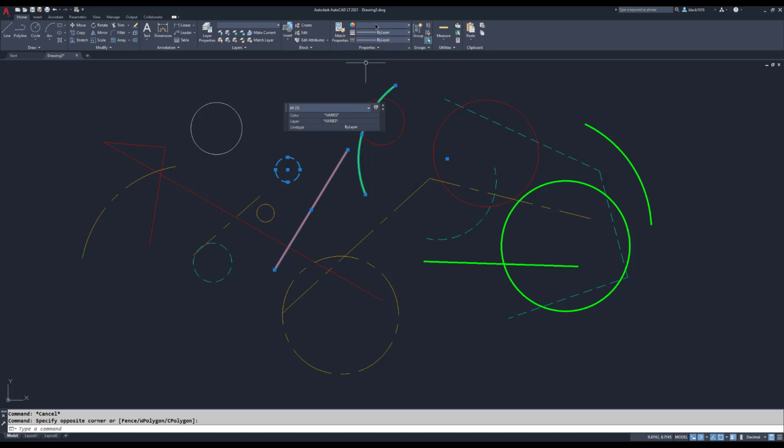Up here, it just leaves it blank. But I can use this to say, you know what, I need to fix everything. I need to have everything controlled by layer because that's what we really should be doing. After I pre-select objects like this, to let them go, you hit the escape key, and we're off and running.